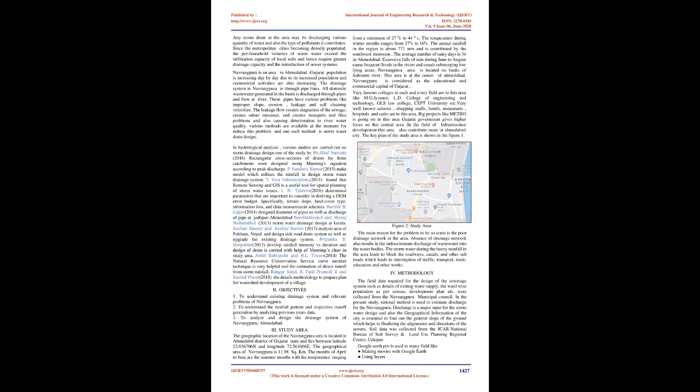Storm sewers, also called storm drains, are large pipes or open channels that transport storm water runoff from streets to natural bodies of water, to avoid street flooding. Storm drains vary in design from small residential dry wells to wide municipal systems. Various storm drainage systems are designed to drain the storm water, untreated, into rivers or streams. A combined sewer is a type of sewer system that collects sanitary sewage and storm water runoff in the same system. Combined sewers can cause serious water pollution problems due to combined sewer overflows, which are caused by big variations in flow between dry and wet weather. Figure 1, Storm Water Catch Basin.